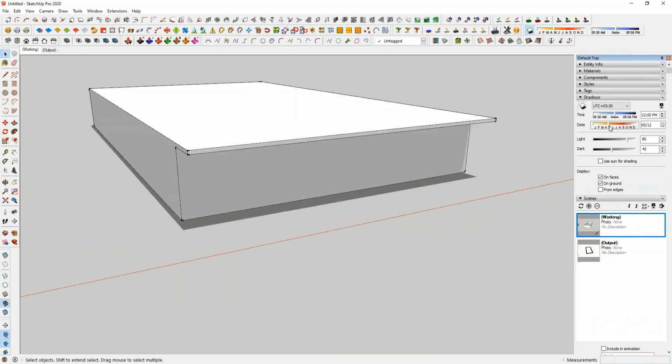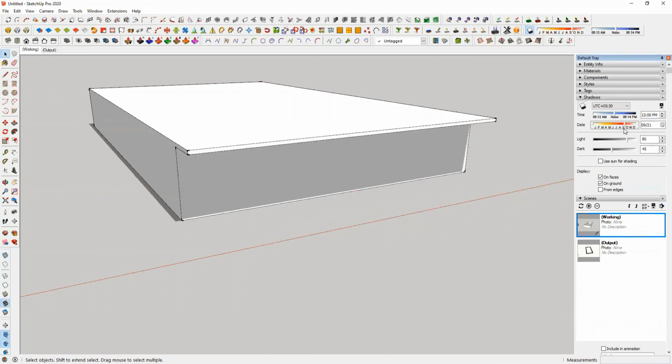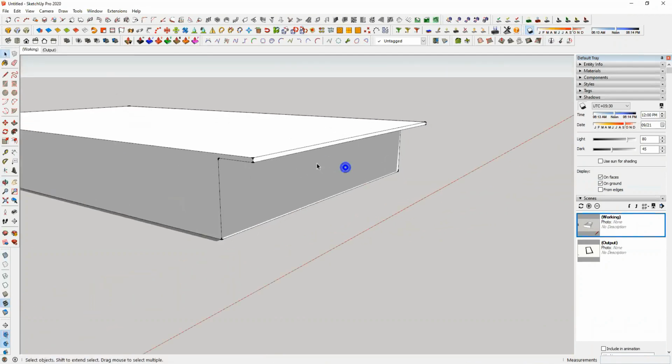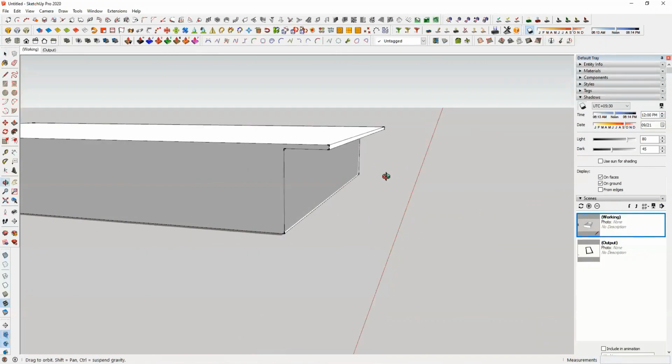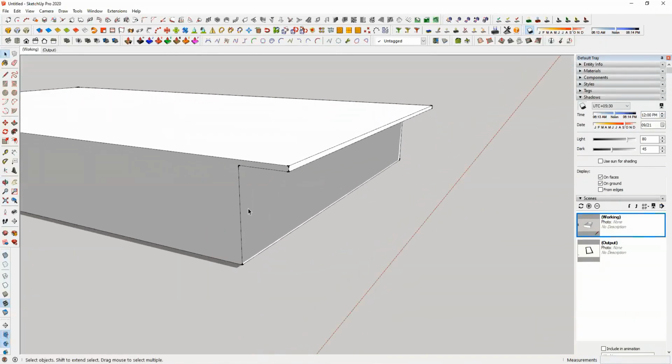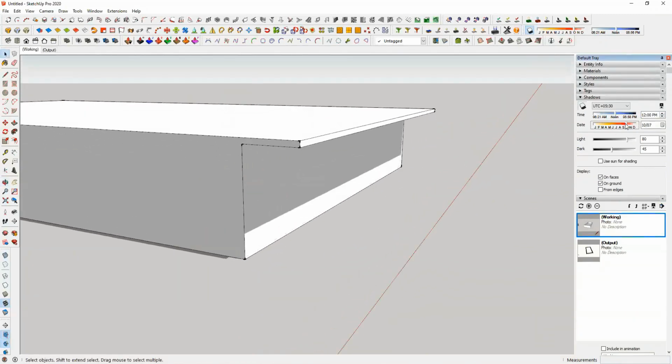So that means from April till next September end, you don't see the direct sun on this facade, right? So this is how we can do a tentative or preliminary study of the projection, so that we have an idea about the shadows and the shades and the sun movement.